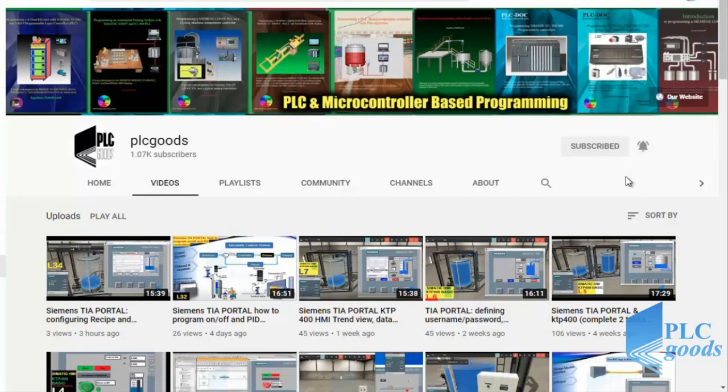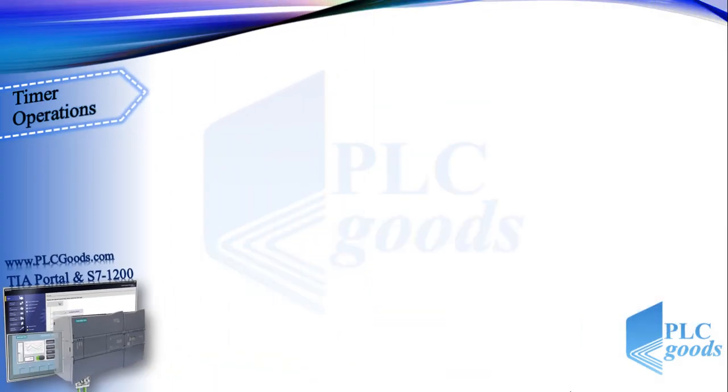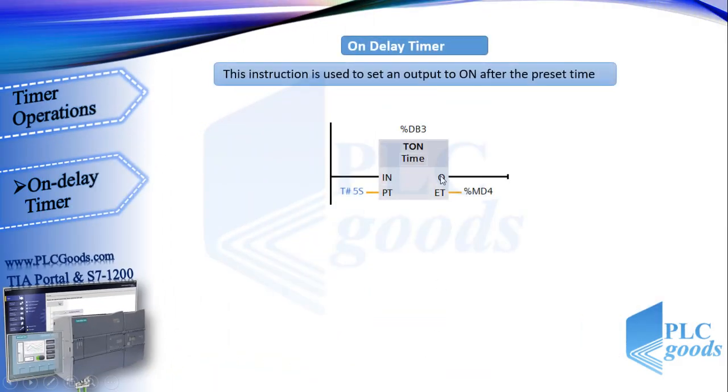Alright, let's start with on delay timer. This is on delay timer symbol in ladder language. We can notice this timer with a small syntax TON. This instruction is used to set an output to on after the preset time. Here, the preset time is 5 seconds.